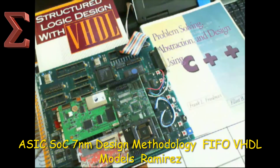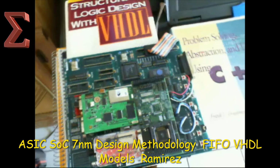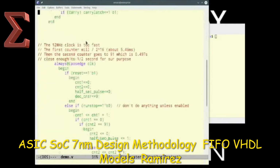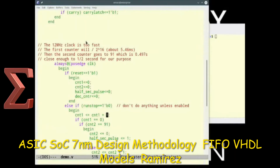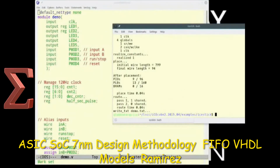And this is how it is done. First, we analyze and elaborate the design. The source code is usually best read in with analyze and elaborate. Executing the analyze command performs the following: reads the VHDL source file, checks it for errors without building generic logic for the design. It then creates the library objects in an HDL independent format, and then finally stores the intermediate files in a location.